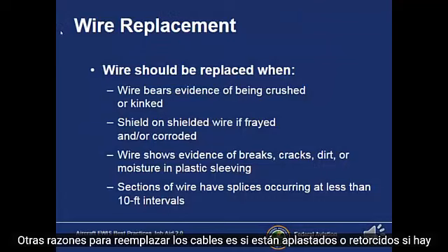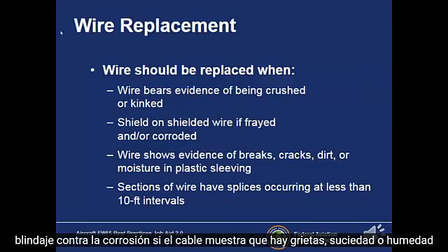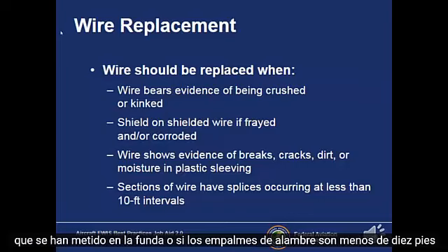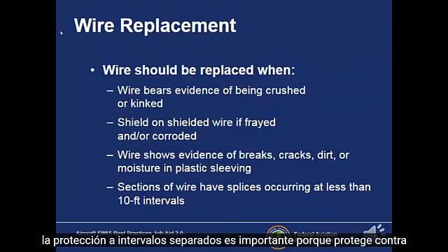Other reasons to replace wires are if they're crushed or kinked, if there's shielding corrosion, if the wire shows cracks, dirt, or moisture that have gotten into the sleeving, or if the wire splices are less than 10-foot intervals apart.